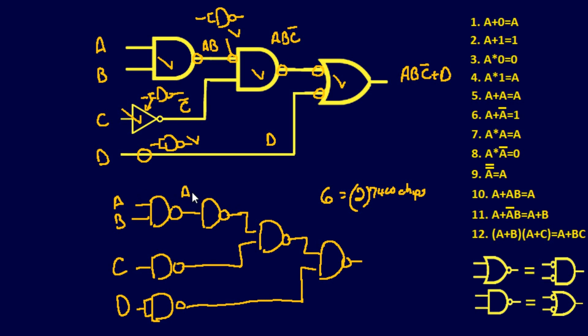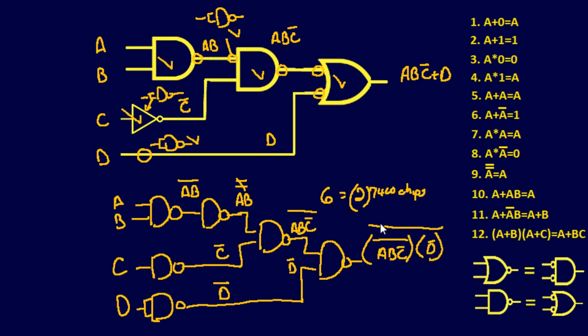So do the same thing we do all the time. AB NOT, which is canceled out, to AB NOT, NOT, C NOT, D NOT. I try to go with the flow from left to right. That way when I get to the very end, they're all accounted for. Okay, another NAND gate, so it's A, B. I'm just going to cancel it out right now. Okay, and then it's C NOT, NOT over the whole thing. And D NOT's right here. So this is going to come out to be an answer of A, B, C NOT, NOT again, times D NOT, and over this whole shooting shebang here.